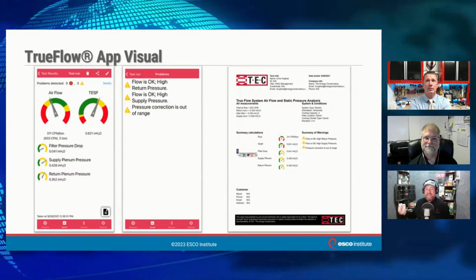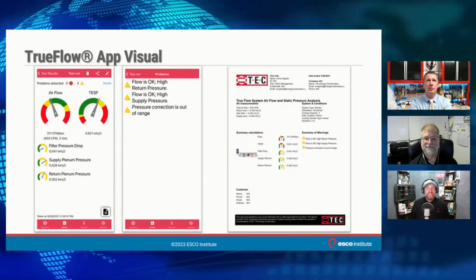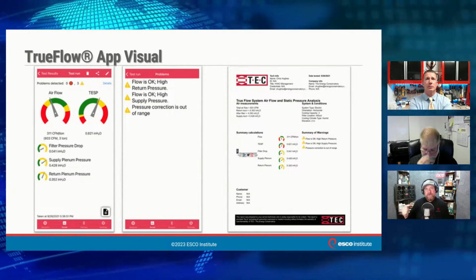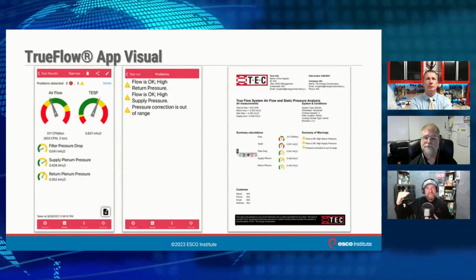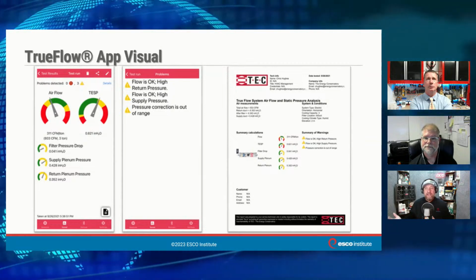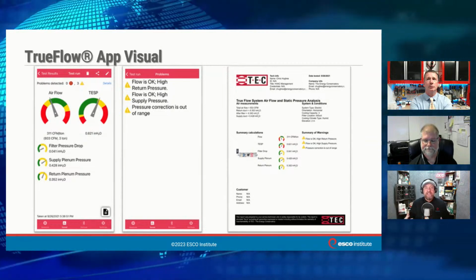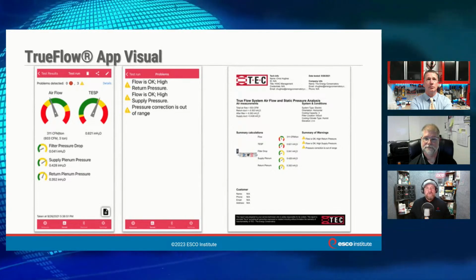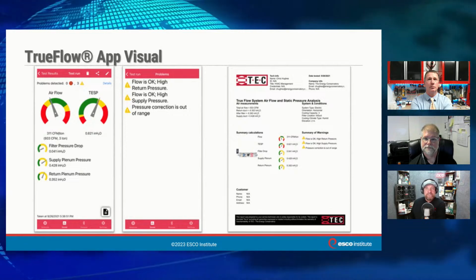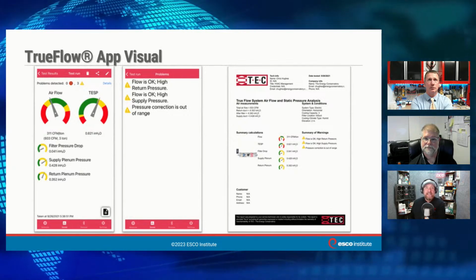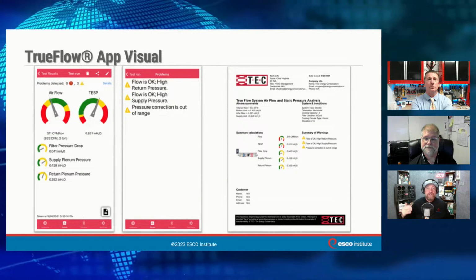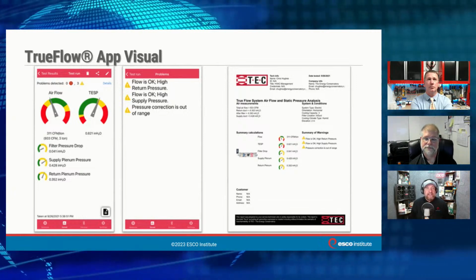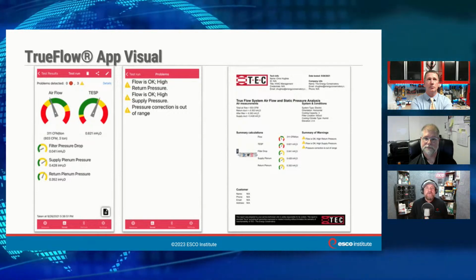So it's got so many different options. One is it just will give you a CFM number, which is super easy and simple to do. Right. But if you put a few more probes in there in different places, it's able to then evaluate where your restriction is or where your most likely problem is. So now by putting it in this red and green, it's telling you, hey, you most likely have an issue in that evaporator coil. So now let's spend the time investigating that, or maybe across your heat exchanger so you can start looking at secondary, or your return is too small. So we got to solve that problem before we go anywhere else.